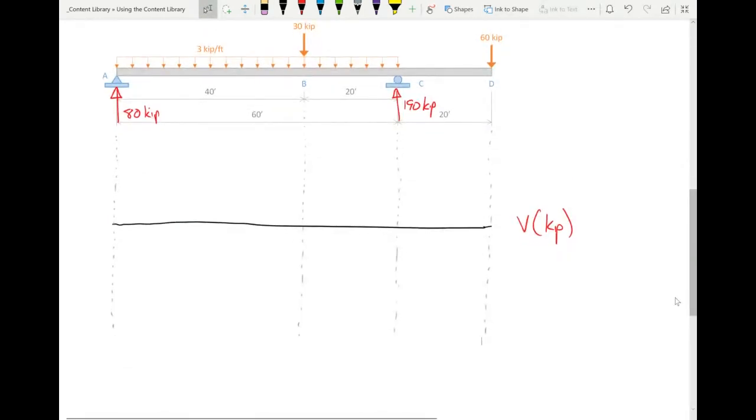Another thing I will point out, and this is probably one of the most important things I really want to make sure you're clear on. If you recall, up there I had that 180 kips right here. Here's the thing. That does not exist on the real beam, okay? What we did is we placed that 180 kips there as a representation of this distributed load. And we did it to make the reaction computation easier.